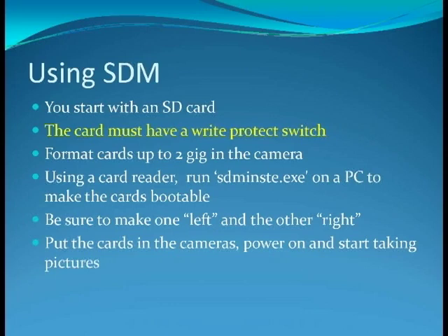The reason this whole thing works is Canon put a feature in their software to load new firmware into their camera. When it sees a memory card inserted, the write protect switch on, and the right buttons pressed on the camera, it will load that software off that card into the camera. A lot of the SD cards you buy, especially the cheaper ones, have given up on that little write protect switch. You have to have a write protect switch to use it.